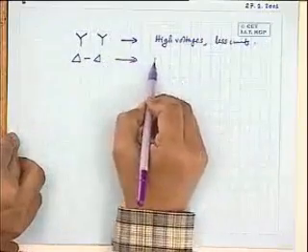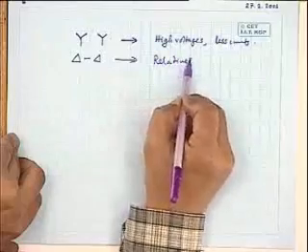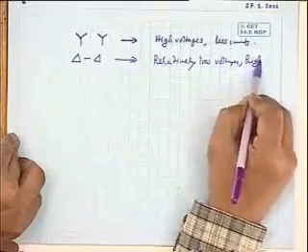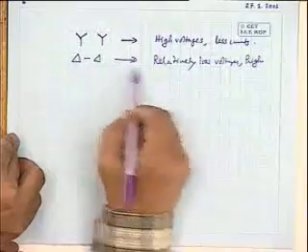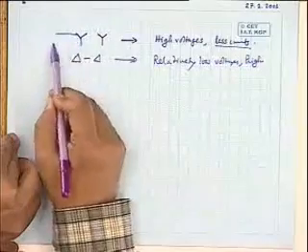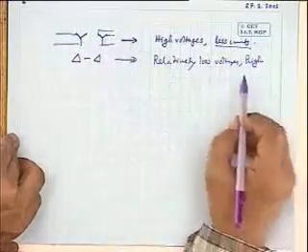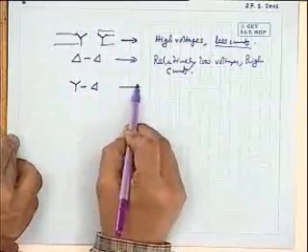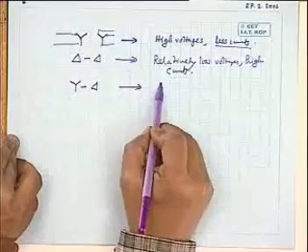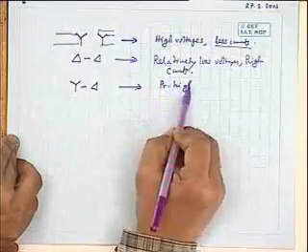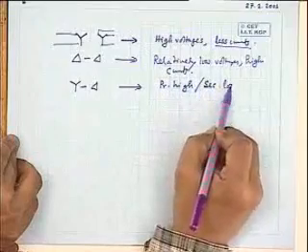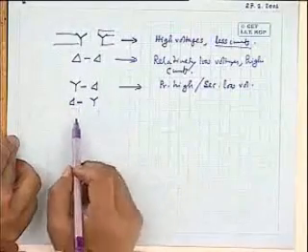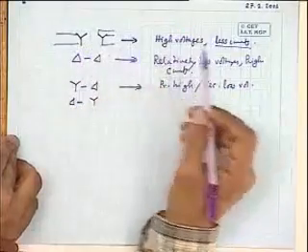Then you have, say, delta connected transformer, generally to be employed for relatively low voltages, and maybe high currents, because currents in the windings will be √3 times less. When I say currents, I mean the line currents. So high currents. And the other combination, of course, will follow naturally. That is, when primary is high voltage and secondary is low voltage, and so on, delta star connected transformer, like that.